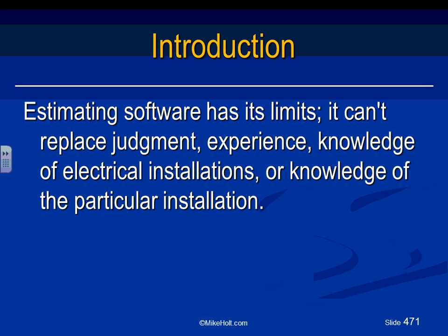what do you use? EMT conduit is one of them. PVC, rigid for severe physical damage, MC cable. These are the major ones, and PVC has 2 types, and rigid has 2 types. So these are, I would say, the 10 wiring methods used almost all the time in commercial work. In residential, of course, especially in Minnesota, we use Romex. Any comments, guys, about software not replacing your judgment and experience? Kerry, does it make sense?